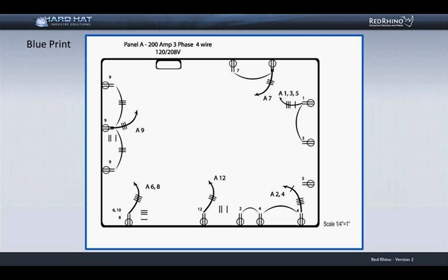Now, returning to the drawing, but before you start, set up the scale X to the scale which matches your project drawings. Pretend my computer pointer is a scale X while I demonstrate how to roll off the takeoff using a scale X. Since several conduits on this drawing are the same conduit size and type and the same number of conductors, I can take them off and enter them into Red Rhino in one entry using the Conduit Wizard.